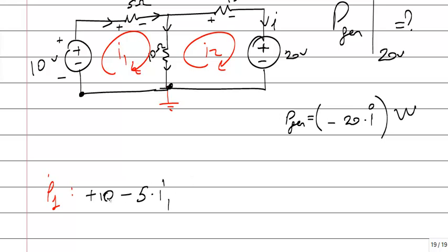Okay. And now, what's the current of this branch? I1 is supporting, I2 is opposing. Okay, I2 is from down to up. So the current downwards is I1 minus I2. What is the current upwards on that branch? Yes, I2 minus I1. So I use downwards. It means this is plus, this is minus. I will say minus 10 (I1 minus I2) is 0.